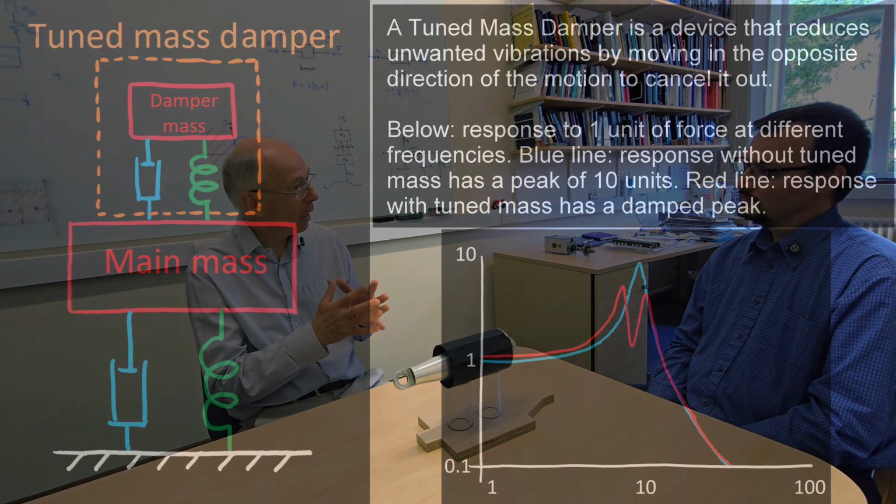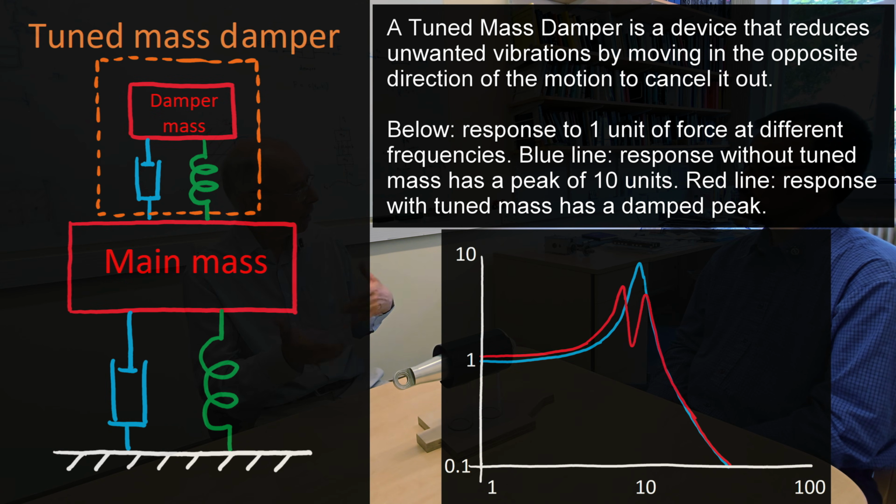Question 2. Is the inerter just a type of tuned mass damper? Again, no. A tuned mass damper is a secondary system, usually a heavy mass on its own spring damper setup that's tuned to counteract vibrations at a specific frequency. It's a brute force way to cancel oscillations by letting one mass, the one of the mass damper, fight the other, the mass of the car.